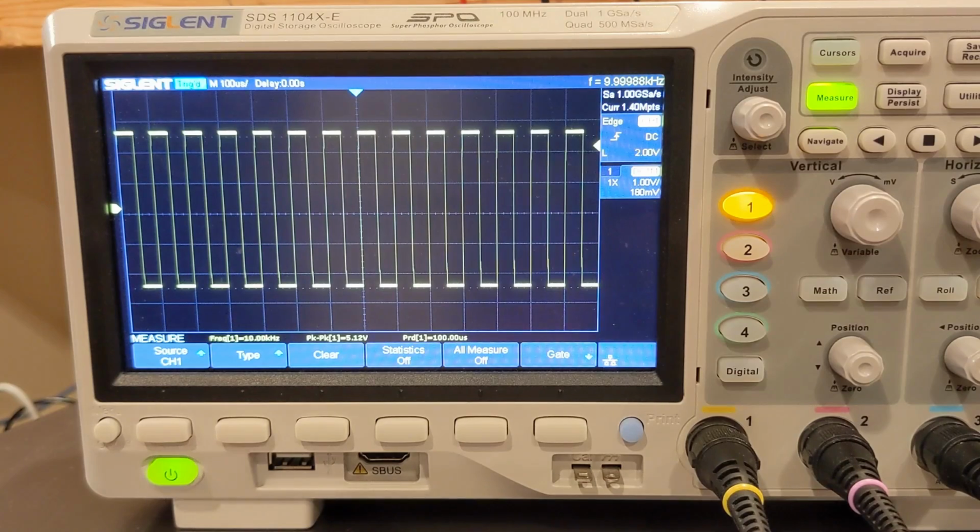The problem that we have right now is this yellow triangle. This is our 0 voltage. So you can see we're swinging positive and negative and positive and negative. That is not terribly helpful when we're working with a system that usually runs 0 to 3.3 or 0 to 5. So what we want to do is we want to move that wave so the entire thing is above the 0 line. That's the first thing I would do.